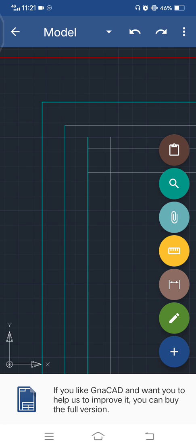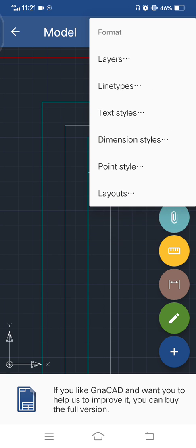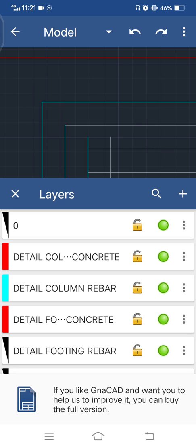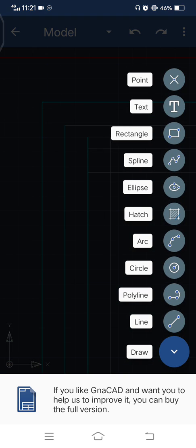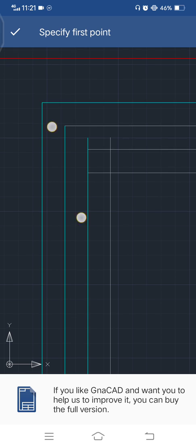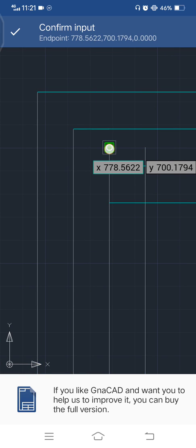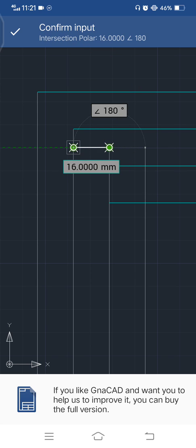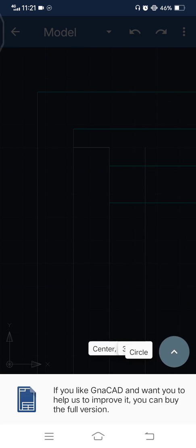First we'll draw a line, a circle rather. So we'll set our current layer into the default, which is yung 0. Yan po. Then click sa current layer, 0. Then we'll draw a line first. Line from this point, first point, up to this point. Okay, and the other side. Check. Then click circle command.